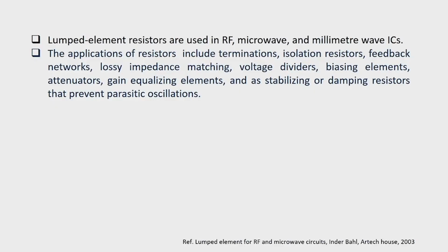Now, resistors are used for a variety of applications, which include termination as isolation resistor, in feedback network, lossy impedance matching, voltage divider, biasing element, attenuator, gain equalizing element, and also a stabilizing or damping resistor that prevents parasitic oscillations.